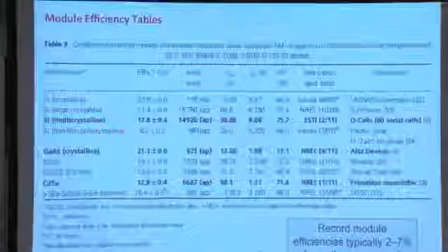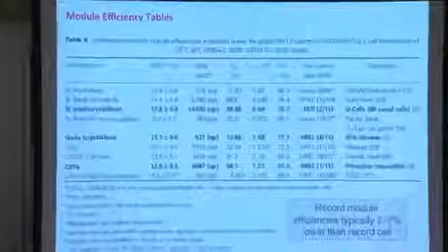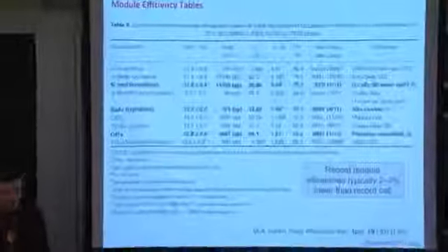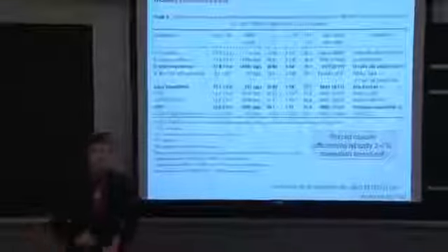Yep, you have a mix of different performers, and when you connect them in series and in parallel, you're going to be limited by the lowest voltage or current, respectively. Did I get that right? Yes. Okay. So certainly there are mismatches between the individual devices inside of a module.